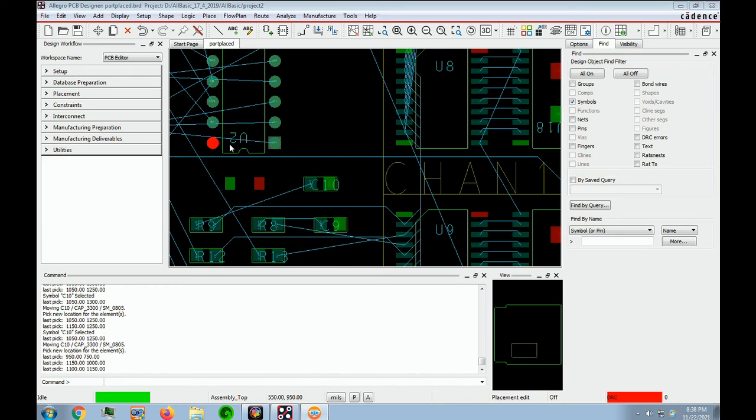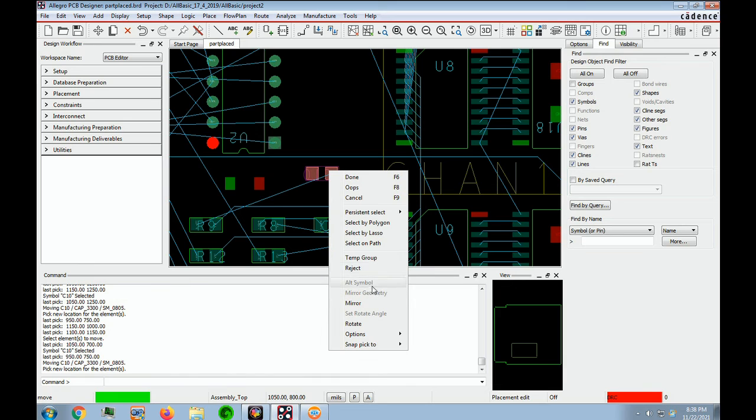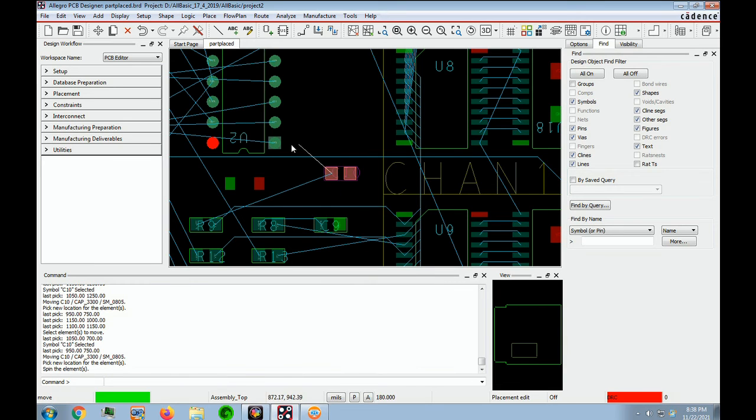And this might be a good component to mirror. We can put that, see how it goes right by the resistor. We say mirror it, and let's rotate it, just like that. So now one via, and that will make the two connections.